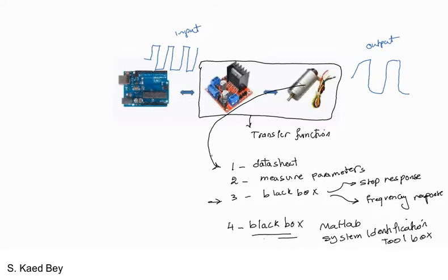And talking about nonlinearities, you could check if your system is nonlinear by, for example, doubling your input and so on, and you can check whether the output doubles as well or not. If it doubles with the same amount, then we could just assume roughly it's linear. Of course, you need more data inputs to verify, but that's the idea.